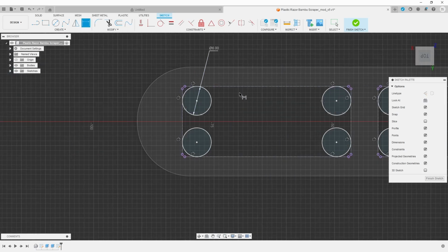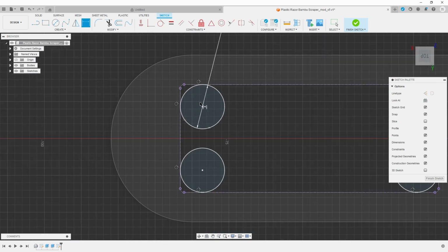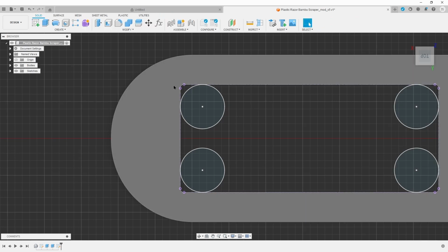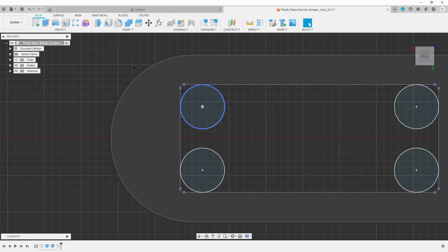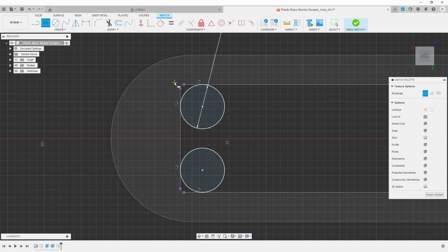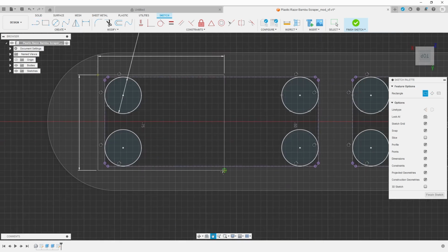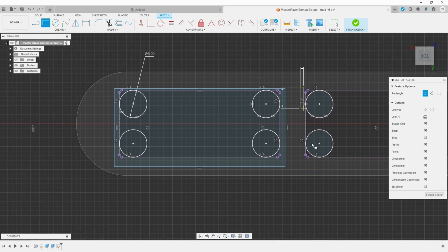Now, in order to fill in those corners, because the geometry that I've projected is construction geometry now, I can't select that corner with an extrude tool yet. I need to have a closed feature there so that it will be selected. So one way is to do the line, but the simplest thing to do is to use a 2-point rectangle and then apply tangent geometry to it.